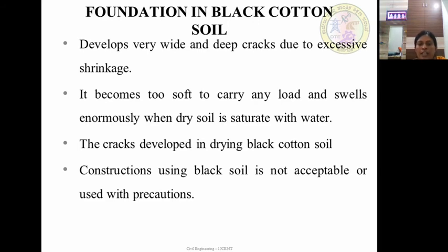Black cotton soil develops very wide and deep cracks due to excessive shrinkage. It becomes too soft to carry any load and swells enormously when dry soil is saturated with water.